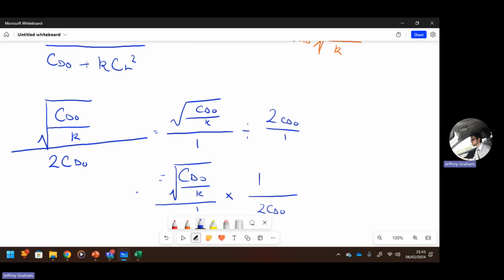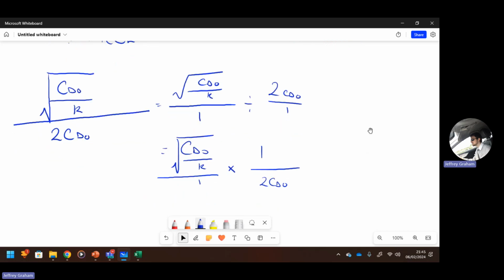Right. Just to keep us on track, all of that now equals an alternative way of saying CL over CD max. So rather than just doing the lift to drag ratio, we've got the condition for CL. We've got a special condition for CD. I've written them as a linear relationship, just so it's a bit easier to see what's going on.